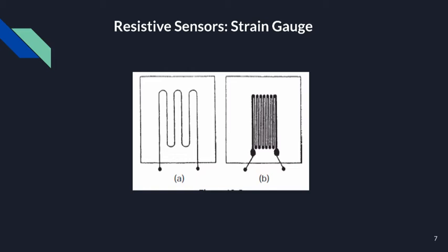In use, strain gauges are bonded to the object whose displacement is to be measured. The process of bonding presents a certain amount of difficulty, particularly for semiconductor types. The resistance of the gauge is usually measured by a DC bridge circuit, and the displacement is inferred from the bridge output. The maximum current that can be allowed to flow in a strain gauge is in the region of 5 to 50 milliamps, depending on the type.